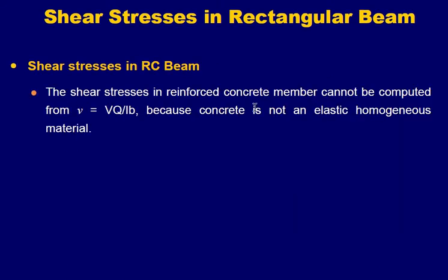The shear stresses in a reinforced concrete member cannot be computed from this equation because concrete is not an elastic homogeneous material. Concrete is an inelastic material. Concrete is non-homogeneous, or you can say that it is a heterogeneous material. So it cannot be applied to concrete directly.